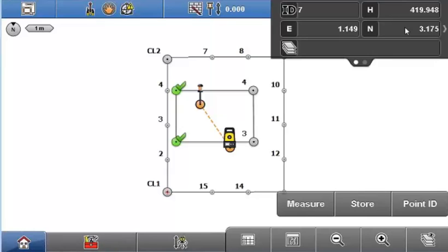Or actually, when Tasha showed you the height transfer, you could enter, instead of the ASL, the sea level, the finished floor level, which would be then, let's say, 1 meter. And from there, again, the foreman would know how much to go down from the finished floor level, which for instance for a cellar would be 2 or 3.5 meters or something like this, and then easily could check this value again in the info panel. So he knows exactly how much he needs to go down. So that would save the often difficult task of doing this with a rotating laser when you're working on a slope, for instance, which is really tough, or with a plumb bob or something like this.